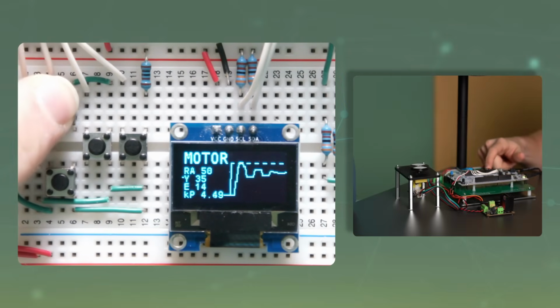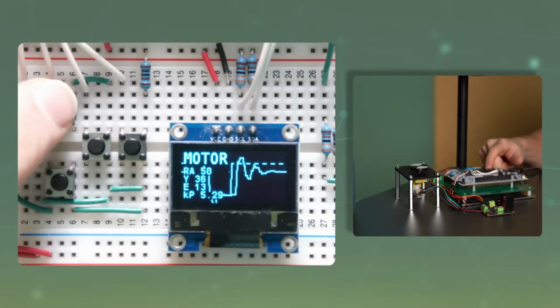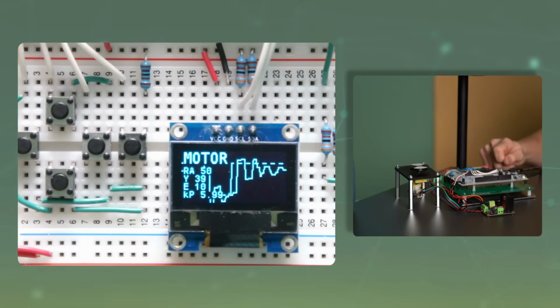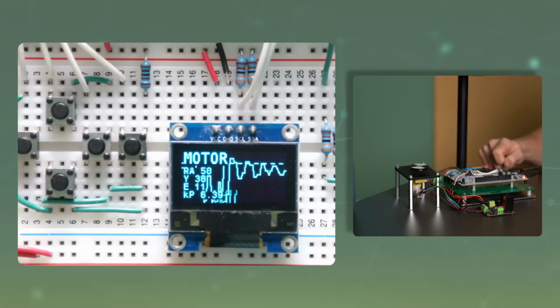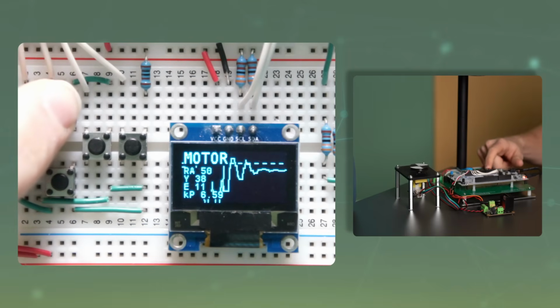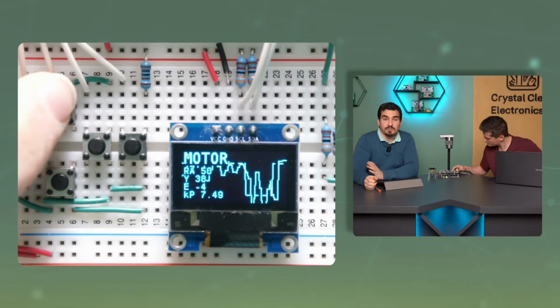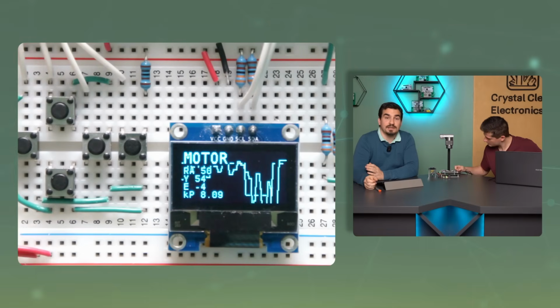You can see that the RPM starts to oscillate. Its value waves back and forth. In other words, it oscillates. We're looking for the point at which this oscillation becomes constant, neither decreasing nor increasing. Here, we can still see that the oscillation is weakening, so we still need to increase the value of Kp. Now that we have found this point, the speed oscillation has stabilized, which is the phenomenon we had to achieve.